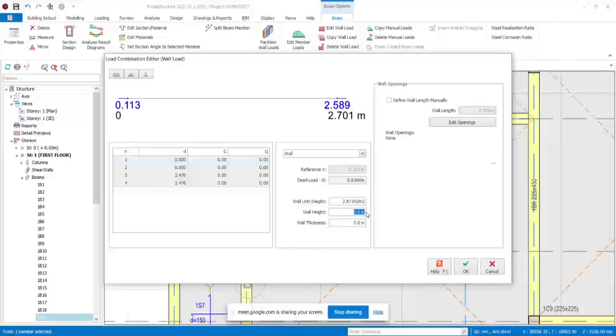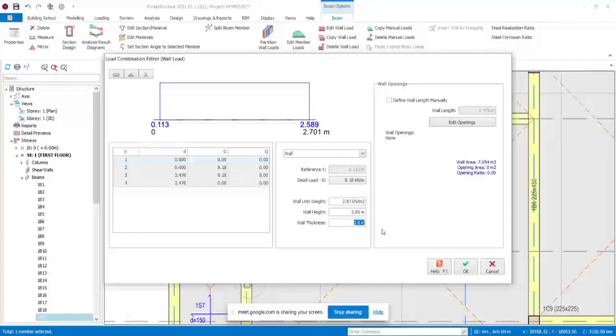The height of the wall we are dealing with, the floor to floor height we input the last time, is 3150. So what you have to do now is to subtract the beam above the floor from 3150, because your wall is going to be under the roof beam. It's going to get to the roof under the roof beam. 3150 minus 450 or whatever it is you make the roof beam as. Alright, so that's 2.7. But I want to make my roof beam 300. I don't want to make it 450. So I want to change it to 2.85. Then the wall thickness is 225.